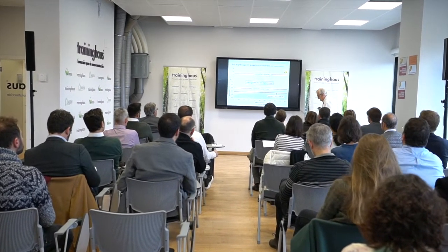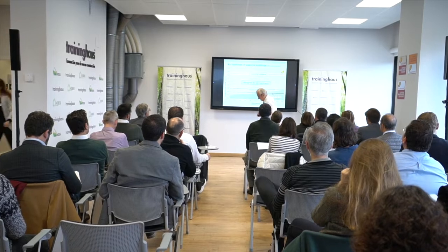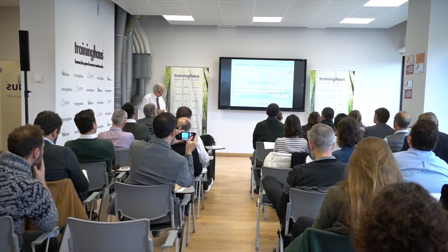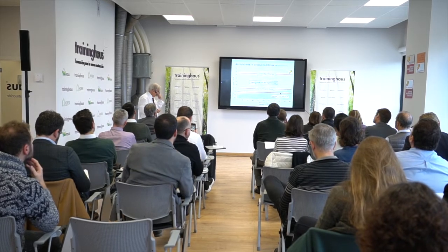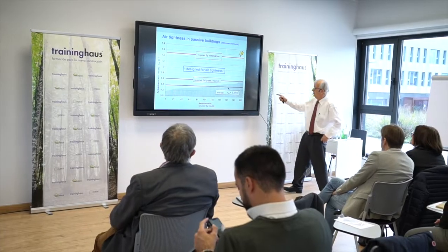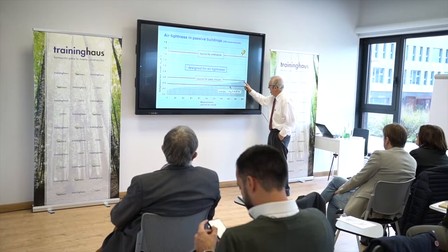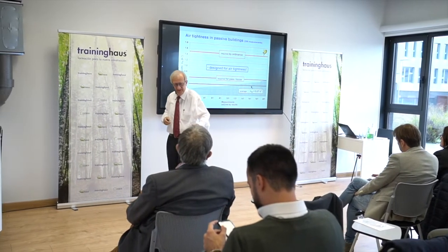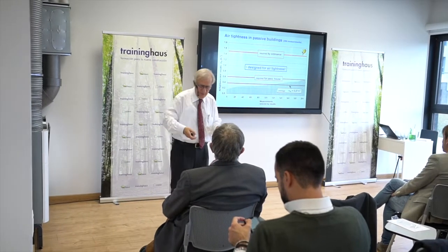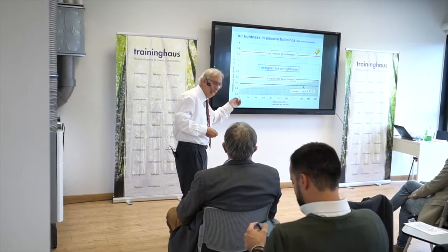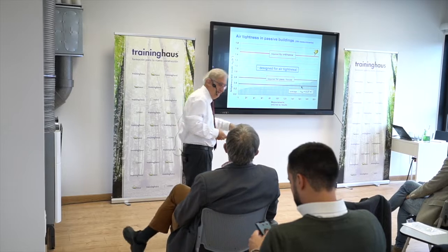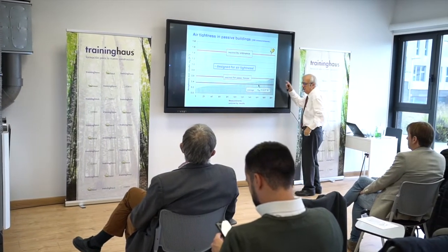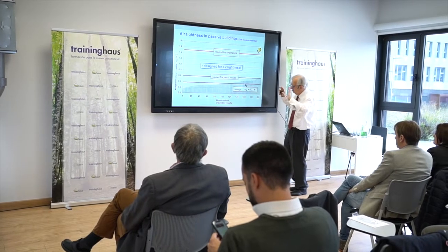We can do really airtight building envelopes. We have proven that now for several decades. There are a lot of measurements being done, especially in passive houses. Yes. Some people say that's maybe cheating, that they have exactly 0.6. No, it's completely okay. Sometimes you do a measurement and you start with a higher value, like Paul has shown you. And then you improve and you do it as long as necessary, and that is the 0.6, or maybe your aim is even lower.